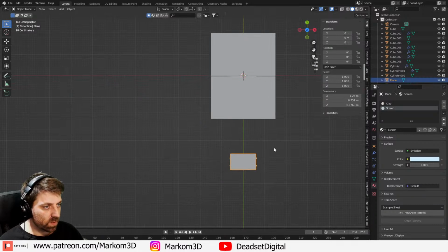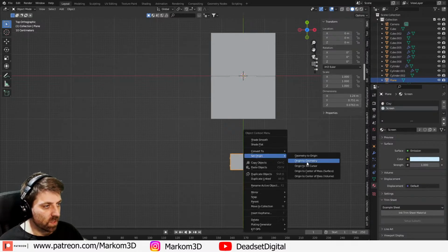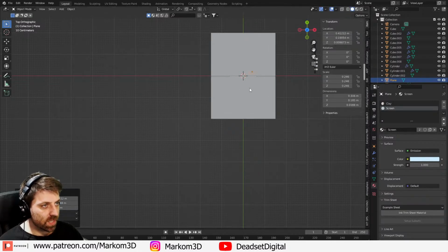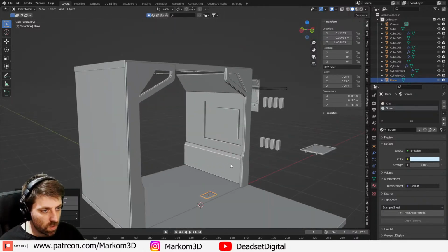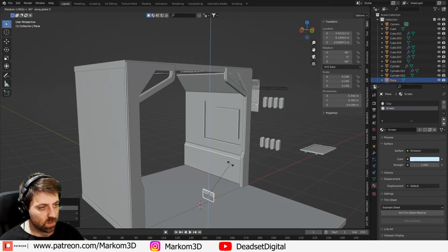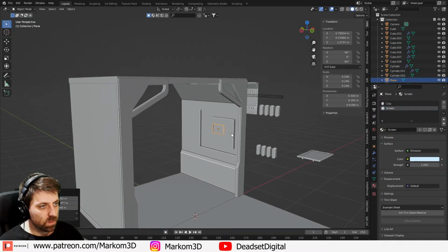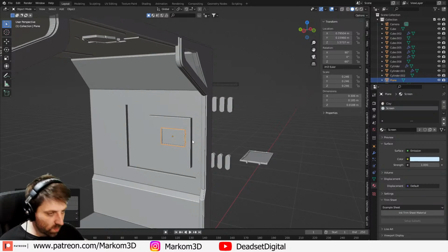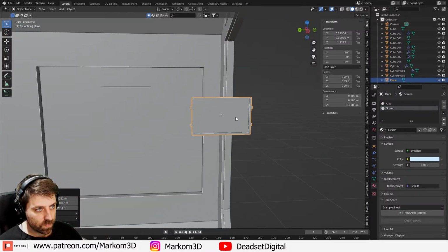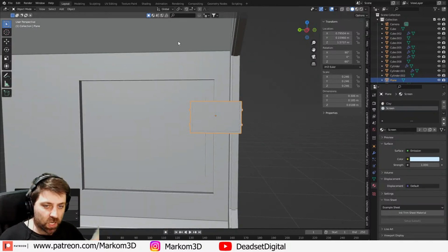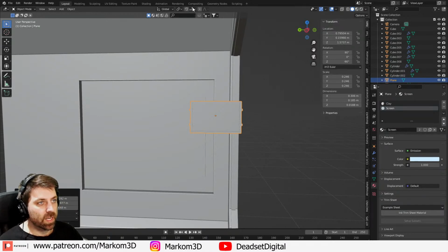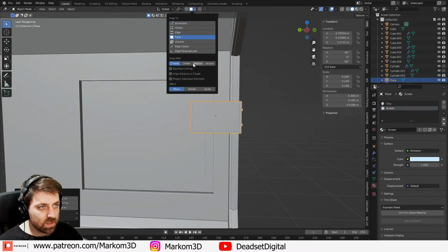And then let's work with this. Right click to geometry, scale that down. Rotate X 90, rotate Z minus 90. Let's go period key to zoom in. Now if I want to do snapping, let's come into face, medium, align to rotation, and rotate.